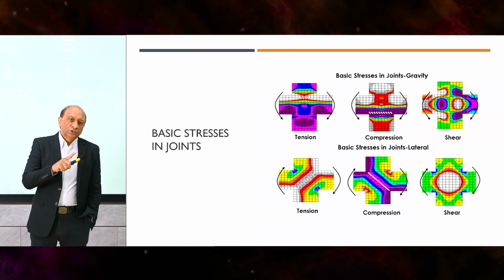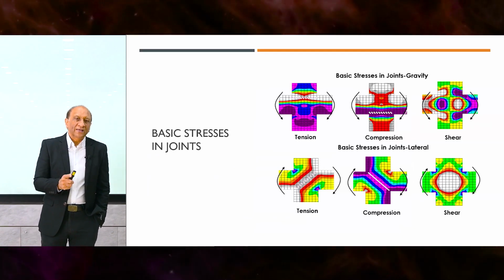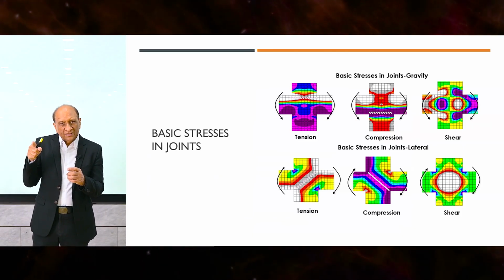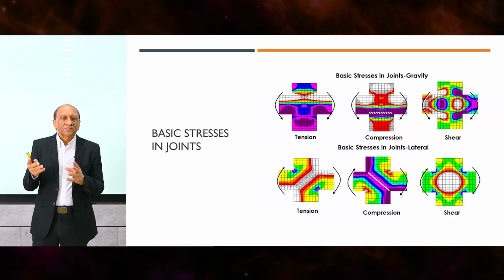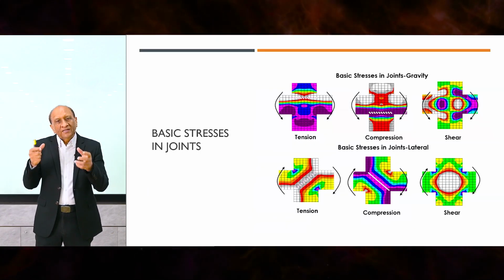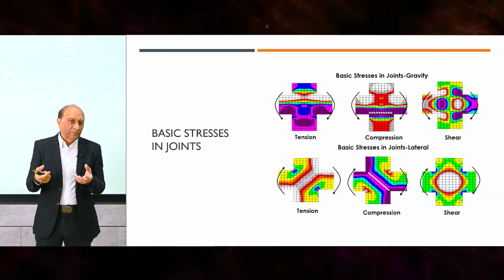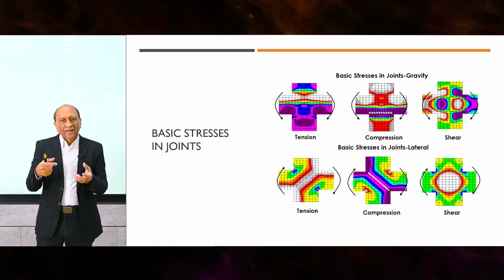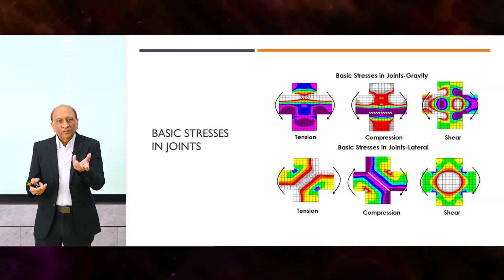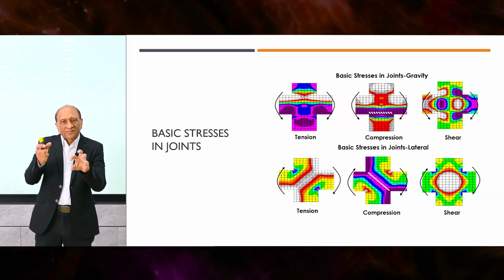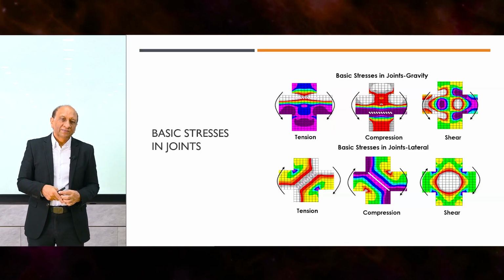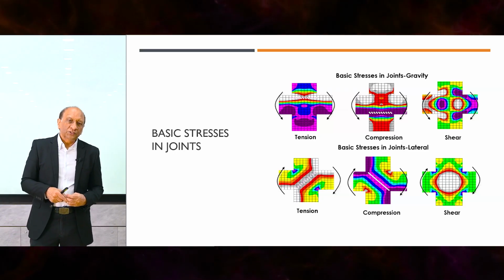Joints. So joints, especially for seismic loading, where the direction of the moment is positive on both sides, will produce diagonal forces on the connection. If you have a gravity load on a joint, then it doesn't matter because you have tension at the top and compression at the bottom passing through the joint. But if you have moment from the earthquake, one is this way, one is this way, both of them in this way, that means they will produce diagonal shear in the joint.